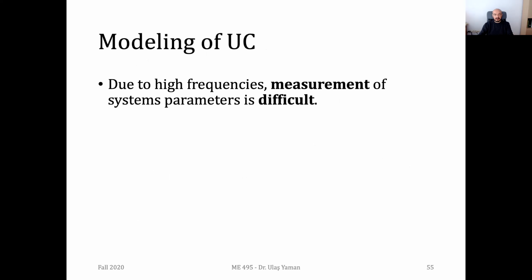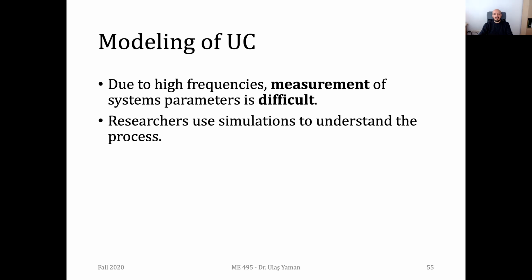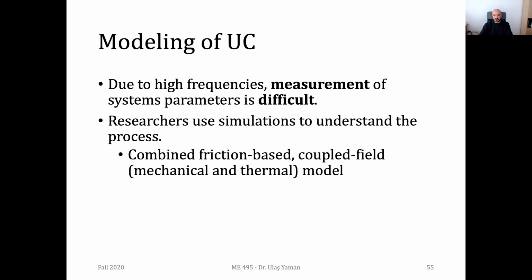So now let's briefly talk about the modeling of ultrasonic consolidation. As you know, we have high frequencies. The frequency is at 20 kilohertz. So doing experiments is quite difficult. You cannot easily measure the forces and other things while you are vibrating your sonotrode at these high frequencies. So that's why we mostly use simulations to understand the fundamentals of this process.